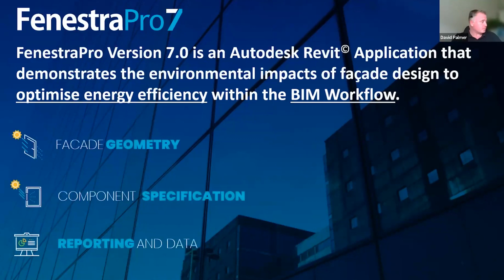As I mentioned a moment ago, we've looked at the facade geometry, which we tend to refer to as that glazing arrangement, that fenestration arrangement, but also the component specification, particularly around those performance criteria. As I mentioned, with glass it's U value, solar heat gain coefficient, and visible light transmittance. When it comes to the opaque elements like your wall, your roof, and your floor, it's predominantly your U value. Again, U values in thermal performance are controlled by code, and obviously you need to ensure you're meeting code while designing your buildings.